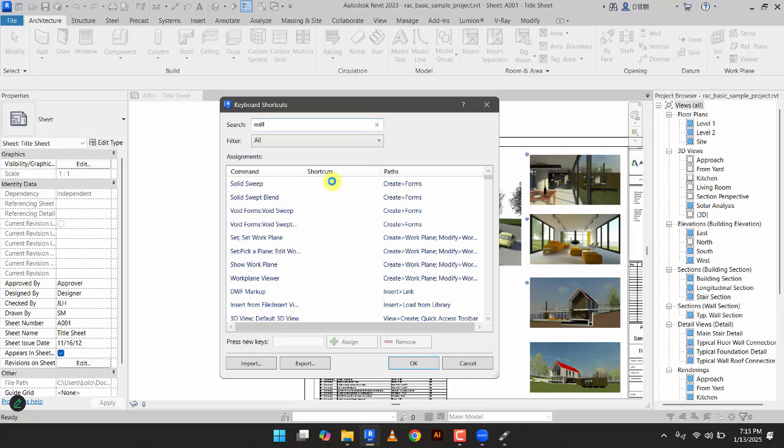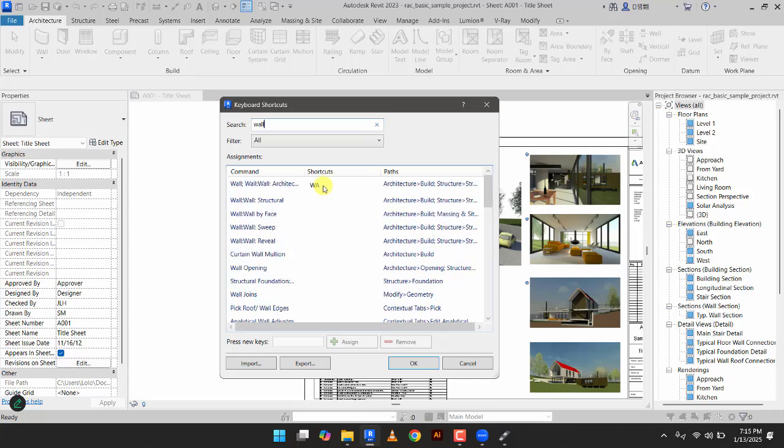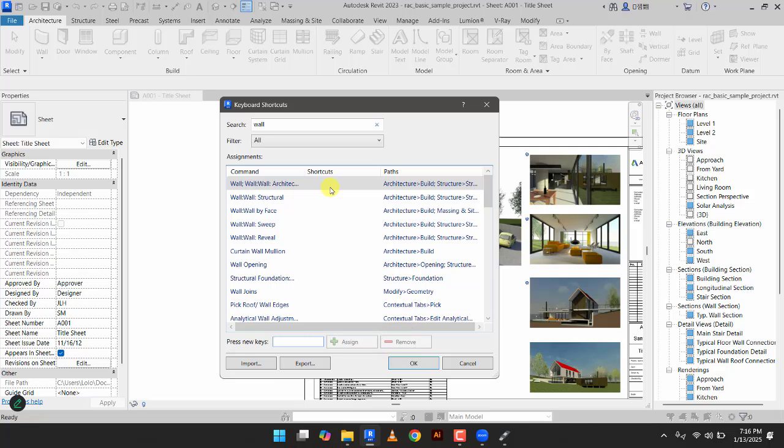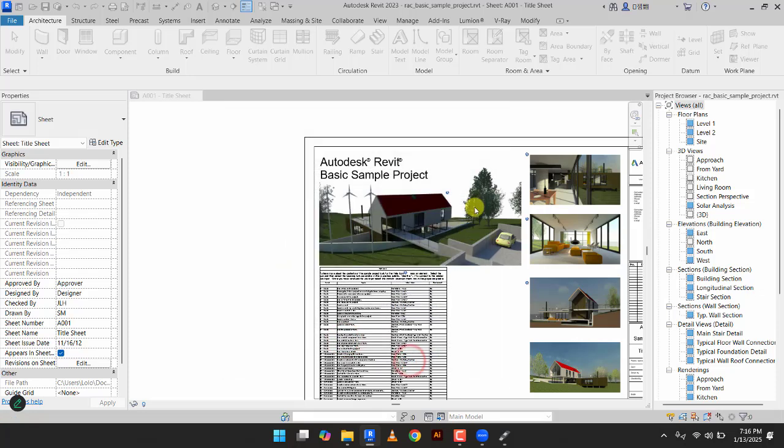Then I'll click on the tool. Then, down here under shortcut, you see remove. Once I say remove, it's gone. Now when I go back, I'll see war with nothing in brackets because I've removed the shortcut. I don't want to remove it, so let me just add, assign, and click OK. Then I have my shortcut placed. Are you okay? Excellent.